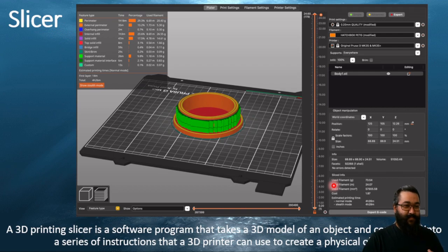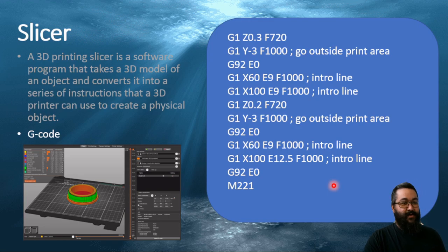So what are these layers that it creates? This is what is known as G-code. It is a code of the geometry of the part, and that allows your 3D printer to interpret the actual part and use the hardware to print it. One of the things you can do with the G-code is change different parameters within the slicer software that will then be sent to the printer. This could be the hot end temperature, or it could be the layers of the actual print itself.